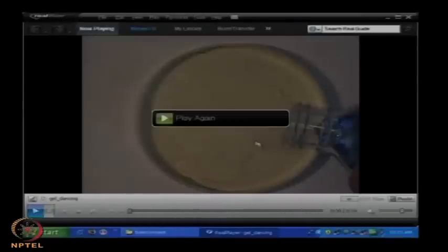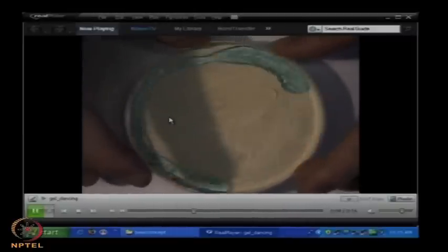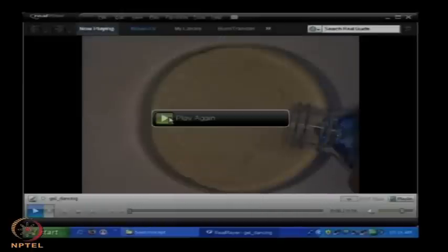But just now we can sum it up to see that here there is some highly viscous gel, and this highly viscous gel is being stirred, and you can see that when it is being stirred it tends to get broken and separated in parts. When it is doing that, of course it is a highly viscous gel, there is an important additional force that is coming into the picture which is making it behave in that way, and that force is nothing but a surface tension force.